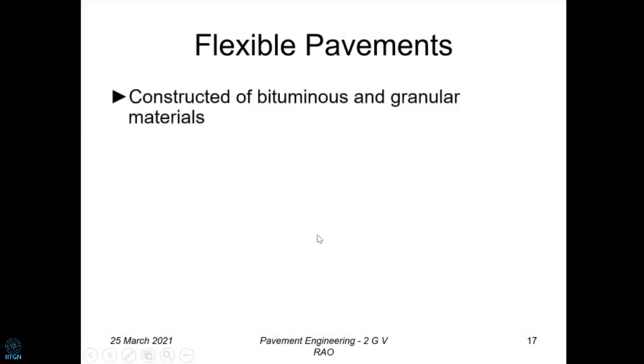So we are talking of flexible pavements, and of course we know that they are constructed with top layers of bituminous material, and naturally between the subgrade and the bituminous layer there are granular layers actually. Another way of looking at it is they are also called unbound granular layers. Binding could be, as we said already, bitumen, or of course in the rigid pavements it's going to be cement actually. So popularly in the pavement terminology, they are called unbound granular layers.